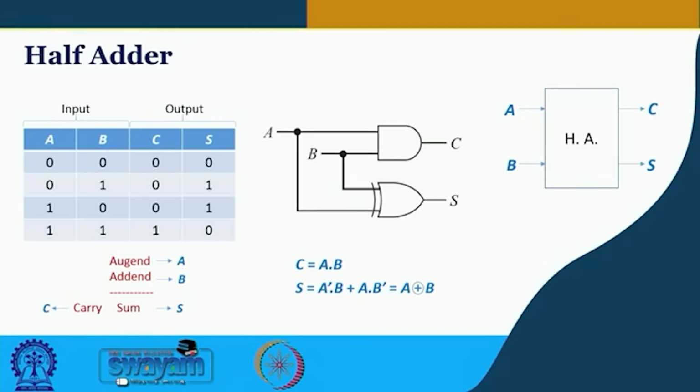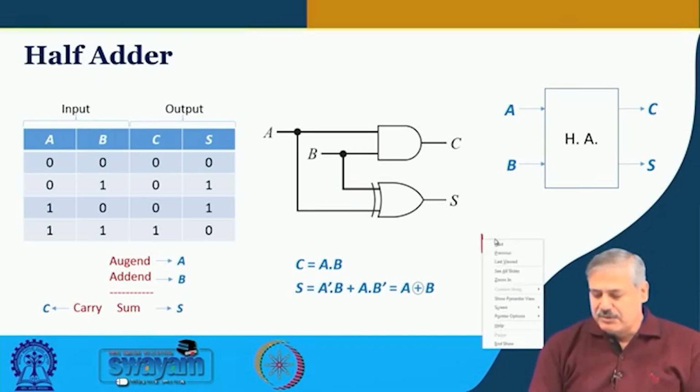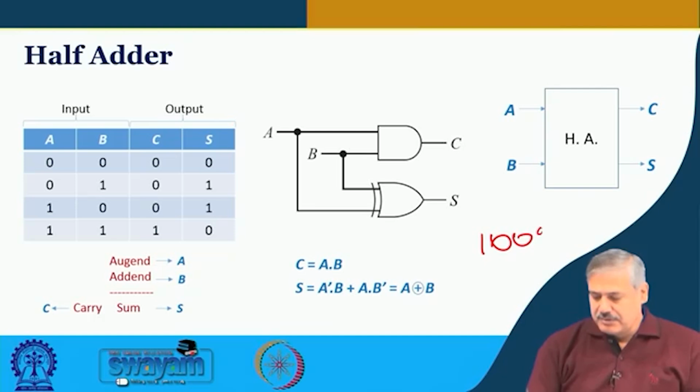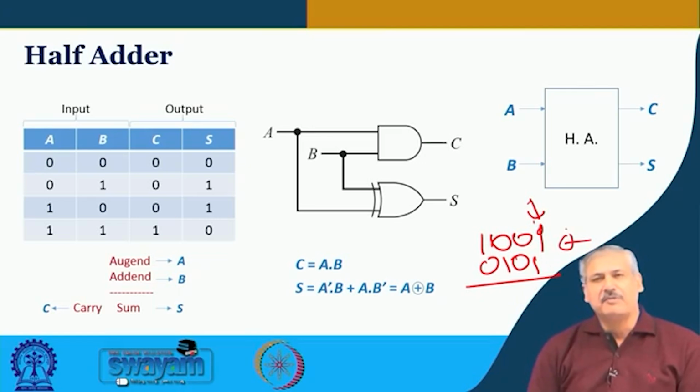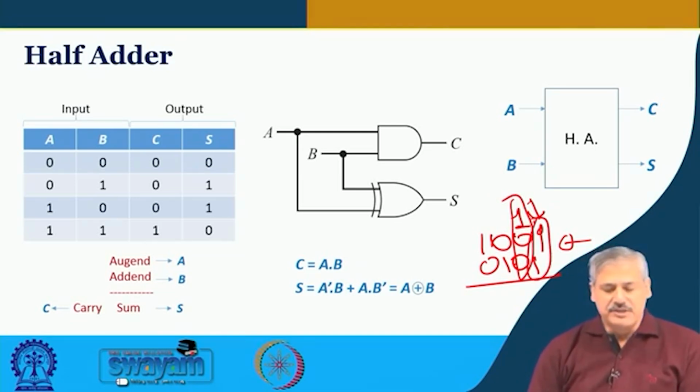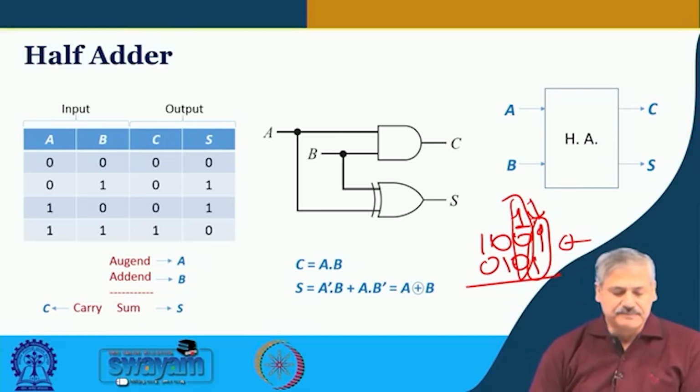Okay. So, if we are considering addition of two numbers, say 1 0 0 1 and another number, say 0 1 0 1, in the first stage when you are adding the units place, carry is not required from the previous stage. So, there comes the usefulness of the half adder. And in the next stage, a carry is generated from the previous stage, so basically there are 3 inputs. In the first stage there could be 2 inputs. So, that is what is half addition.